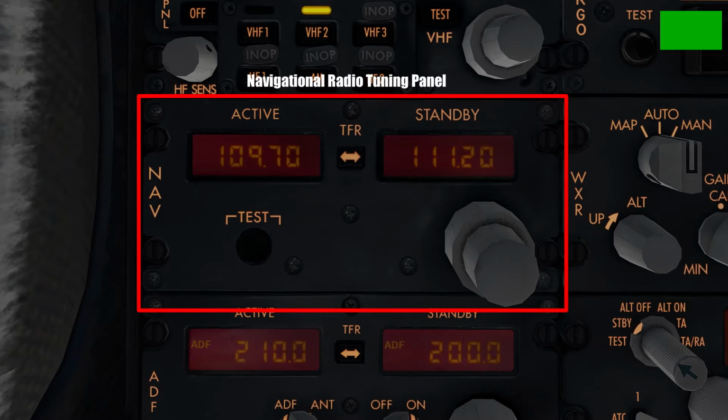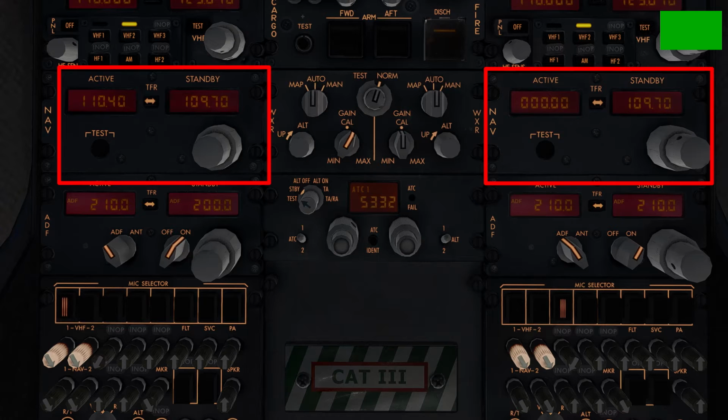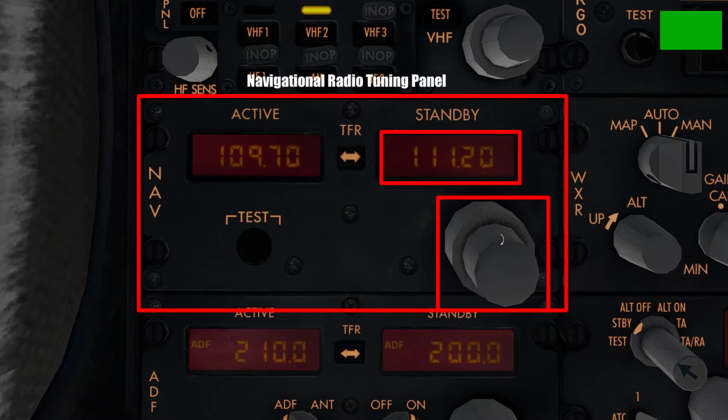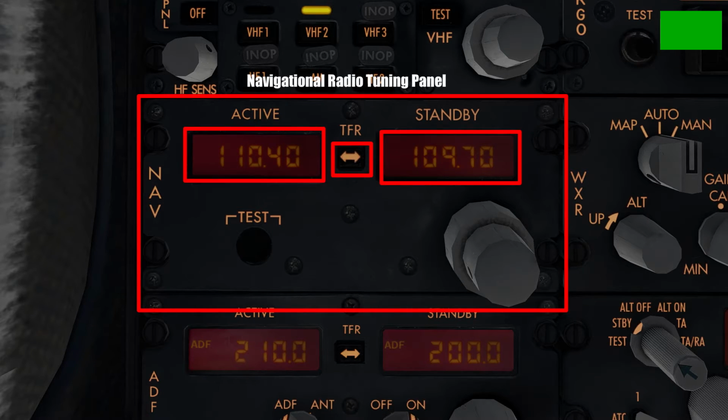Just like the communication radio panels, there are two navigation radio systems in the aircraft, one on the captain's side and the other on the first officer's side. You can again use the larger knob to adjust the numbers before the decimal place and the smaller knob to adjust the numbers after the decimal place in the standby display. Additionally, you may press this transfer switch to swap the standby and active frequencies.